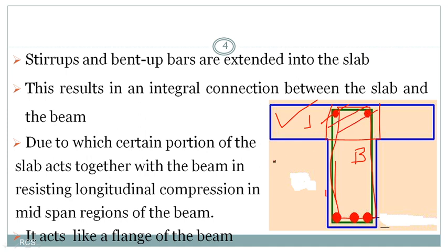Let us say you know that this is the neutral axis of a T-beam. Assume that this is acting here. Above the neutral axis, we have a compression zone. As we are providing reinforcement here, it is a tension zone. Right? Generally, the portion of the beam in the compression zone is like this only. This depth will give the portion of the beam in compression zone.